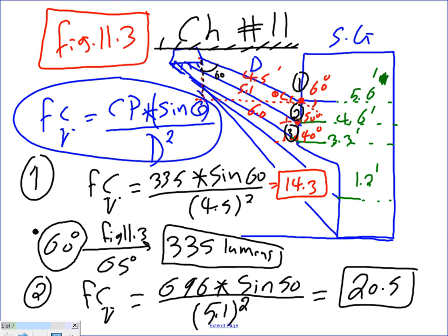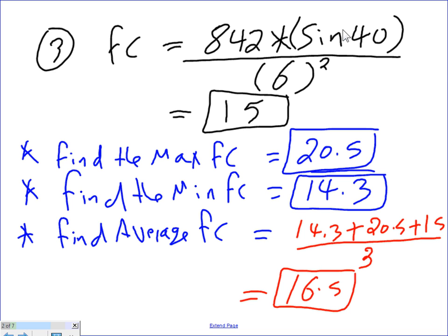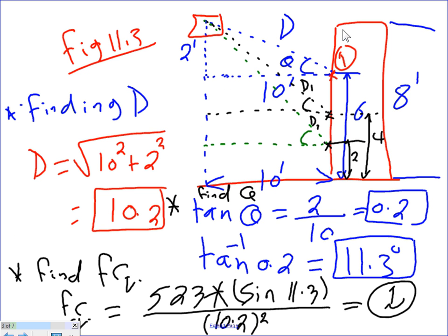Okay, so that's now. Actually, you would never be able to solve this problem unless I give you a graphic like this, guys, with angles and foot candle and candela power. So this one is for a fixture that's actually an F34 T8 fluorescent. Any question about the maximum, minimum? Just find the maximum number, minimum number, and average them. Okay. Here's another example.